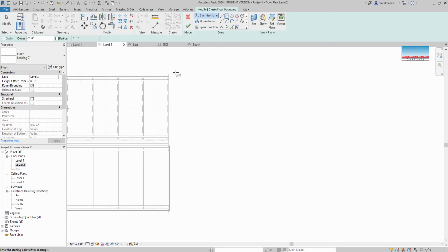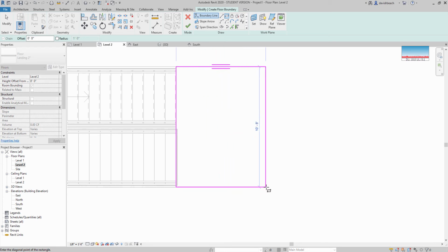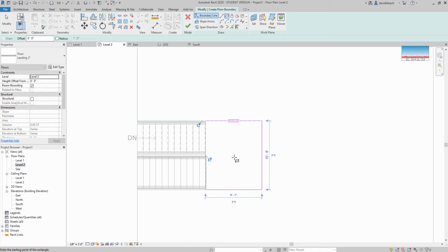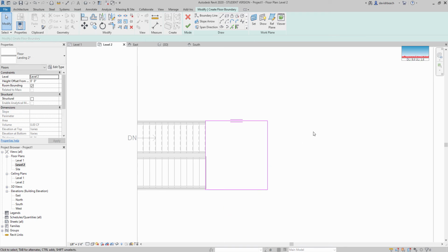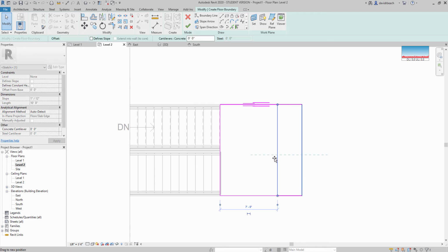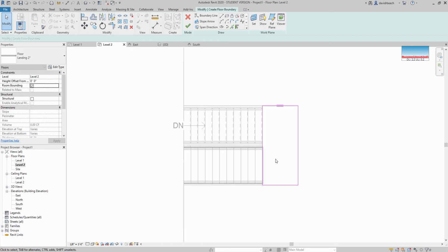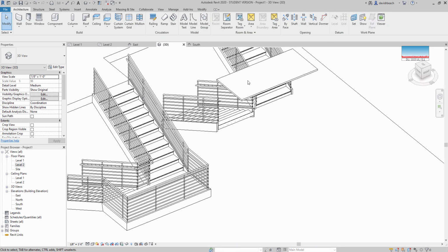So then I can just build this as a very quick box, going edge to edge. And so essentially this is just coming together as a landing for this U-shaped stair. That's enormous. I don't need it to be that big. By code, I believe that's a 5-foot wide stair. It would need to be a 5-foot deep landing. So I now have that.